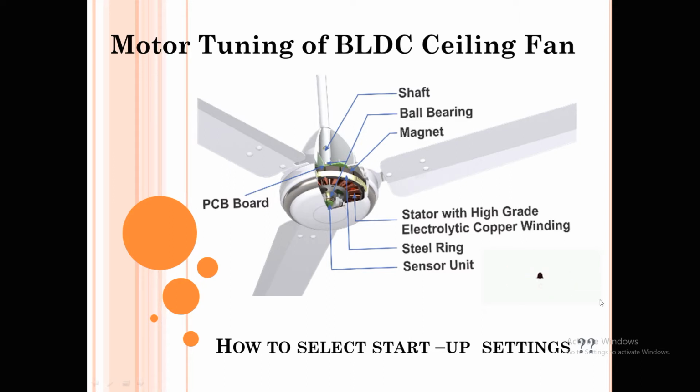And then we discussed the PSD settings and the different startup methods that are available with the BLDC motors. We went through the Align and Go method, and then we discussed the PSD. PSD utilizes the inductive sensing method, and we discussed how inductive sensing actually works and how the internal algorithm works. So we have discussed all those points in our last video. If you're not able to watch that video, please go ahead with that. First watch these videos, then you can come and continue this video.